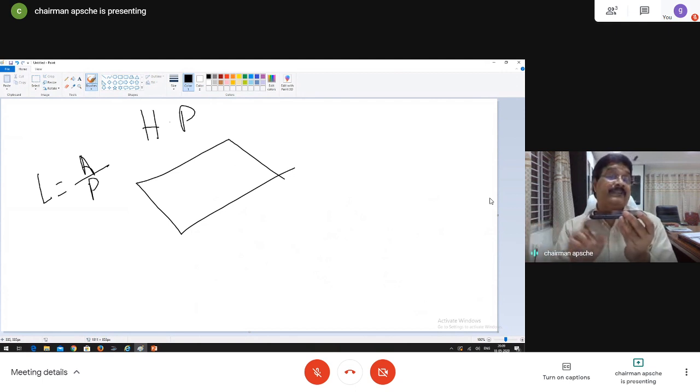Okay, but bottom surface hot is not good. And at the same time, for a horizontal plate, colder top surface is not good for convection heat transfer. Unfavorable condition. Whereas if it is cold at the bottom, what happens? Hot fluid comes in contact with it, loses its temperature, becomes heavy, and straight away comes down, like your deep freezer at the top. So, at the bottom, when it is cold, it is favorable.